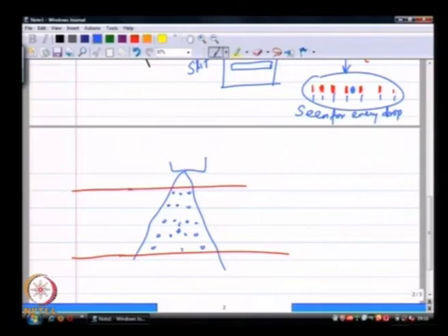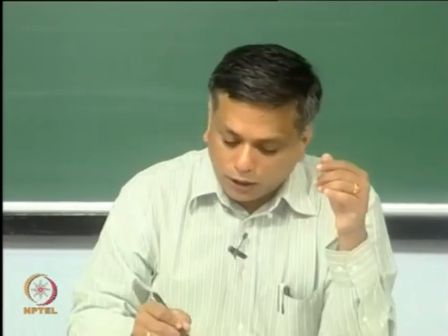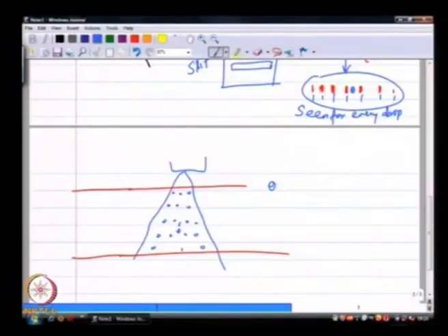So, if I use LIDS, which is laser interferometric droplet sizing, along with double pulse photography, where I take two pulses and get two images slightly apart in time, because I am able to uniquely identify every drop in this image, we can calculate the velocity vector of every one of the drops.